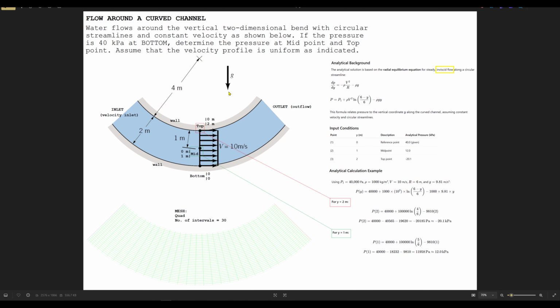To capture that hydrostatic effect, we will define a new variable called pressure, using the formula of absolute pressure minus density multiplied by g, 9.81, multiplied by y, I mean in this direction. This equation simply adjusts the absolute pressure by subtracting the hydrostatic component rho g y, so that we can get the true total pressure distribution in the vertical direction here.